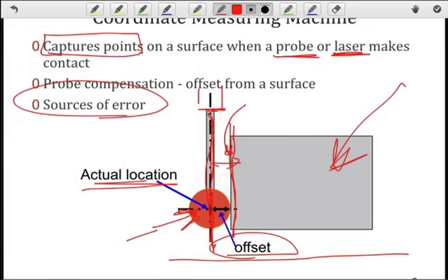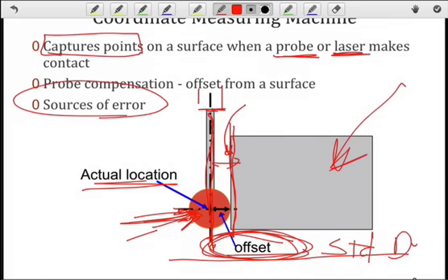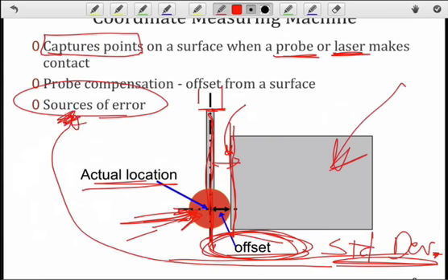And so when you initially used the coordinate measuring machine, what you did was qualified that probe by touching off on a standard sphere, and then it reported back to you what the radius of the probe was, and it also gave you the standard deviation for the probe. And that gives us an idea of the contribution of the probe to the errors that we're going to find when we actually measure surfaces.